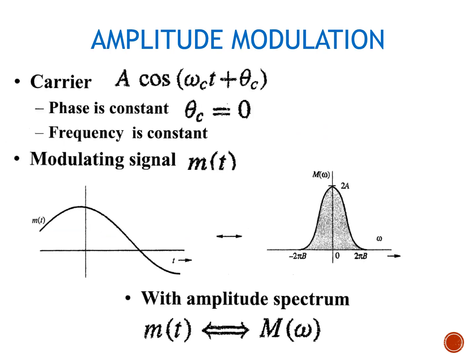So let's look into some expressions of amplitude modulation. This is the carrier that we will be modulating. It's basically a sinusoidal signal. It has a radian frequency of omega c. It has a phase, generally with respect to some reference, which we will consider as 0 for most of the discussion. The modulating signal is m(t), for example represented by this plot.